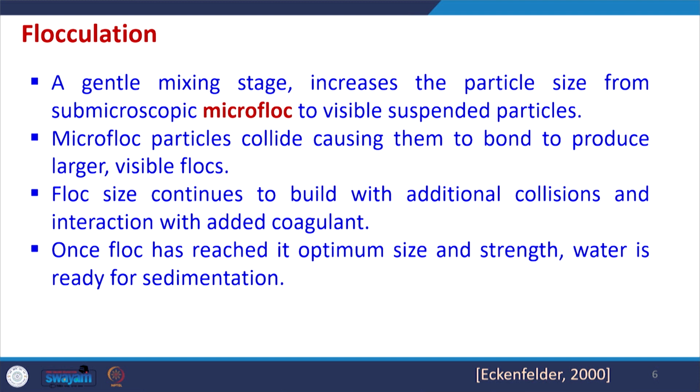Now, since two colloids have come together, we want the third colloid to also come and form a bigger flock, but we do not want very rapid mixing, otherwise these flocks may separate out.